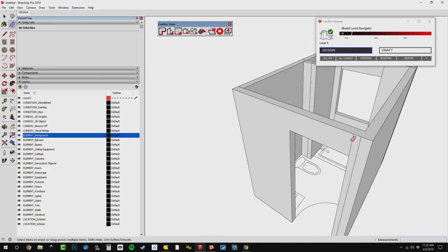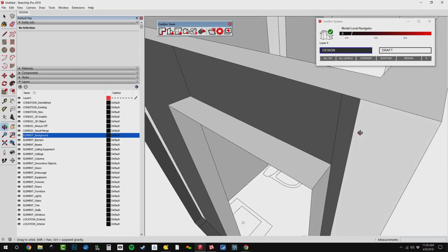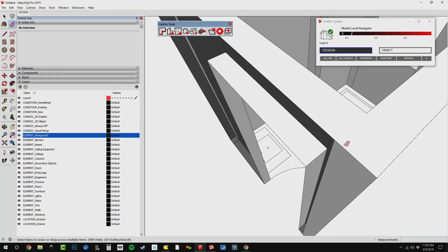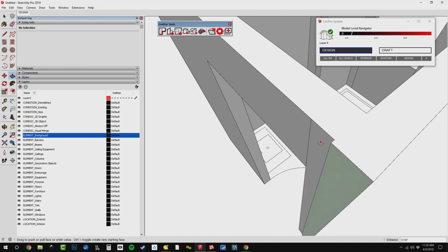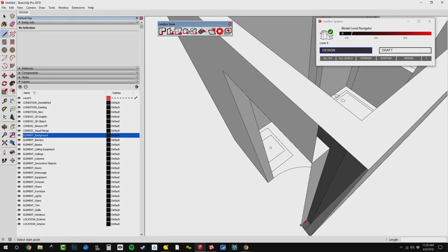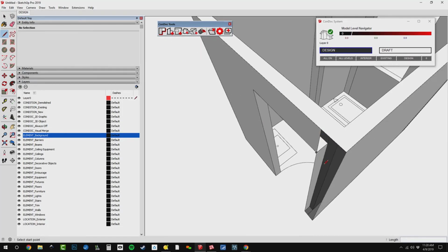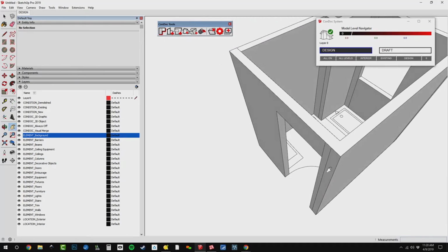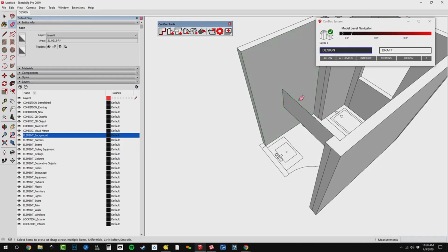So let's just get a little bit of this cleaned up. And let's see, I think I goofed on my little edge there. So let me undo that, double check this. All right, like that. And let's just use a reheal command, and if that doesn't do what I want it to do right now, I kind of goofed up my geometry there. I know what I did. All right, let's try this. I'm going to do a quick rebuild on this guy here.